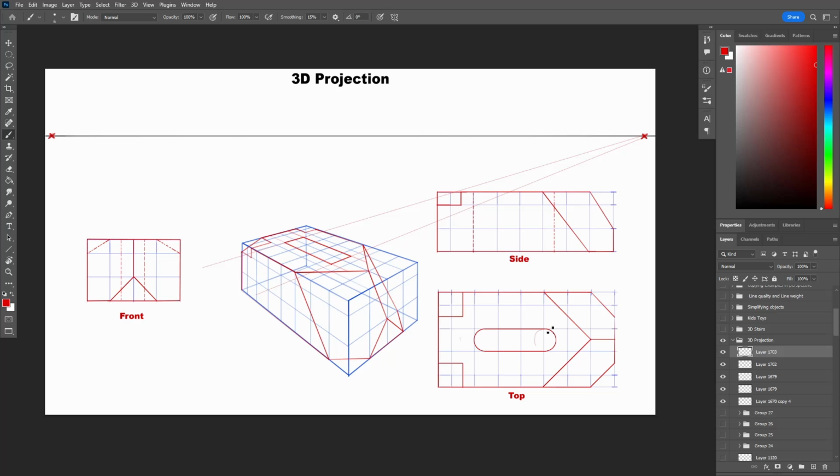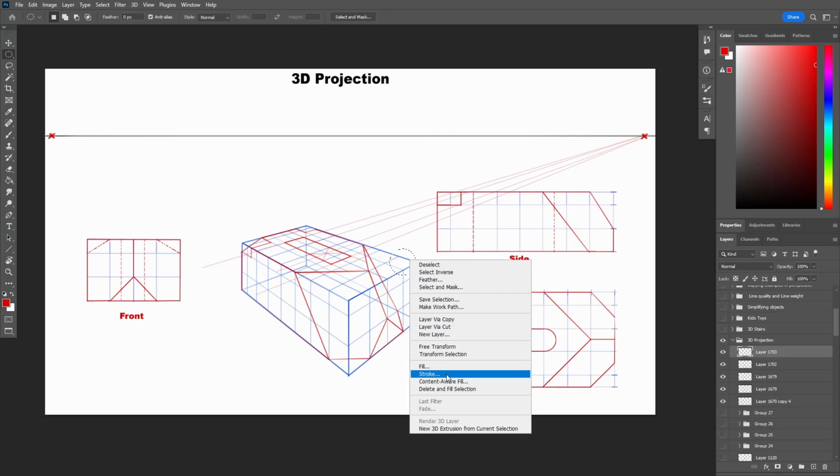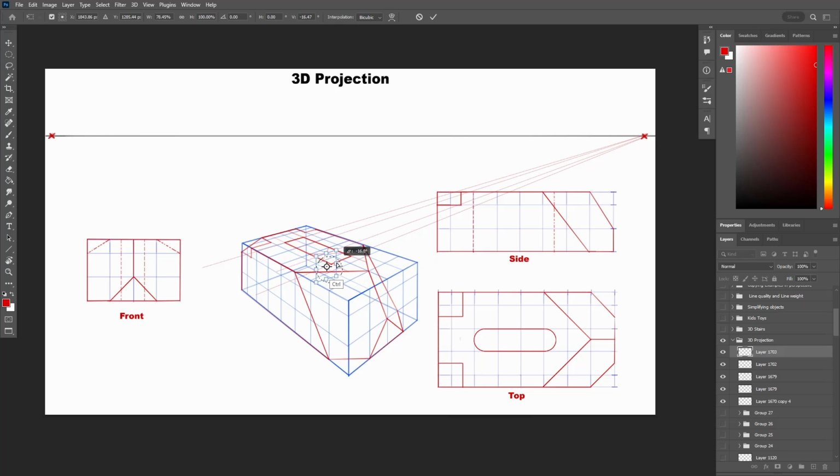Once we have the rectangle, we can draw 2 ellipses on each side and delete half of them to get half of the ellipse on each side. So to do that, we need to find the rectangle surrounding each circle on each end. So let's divide a unit on each side and find the center for it, and draw the ellipse on each end. Once we have the ellipse, we can remove the interior half of it and connect it to the other end to get our smooth rectangle.